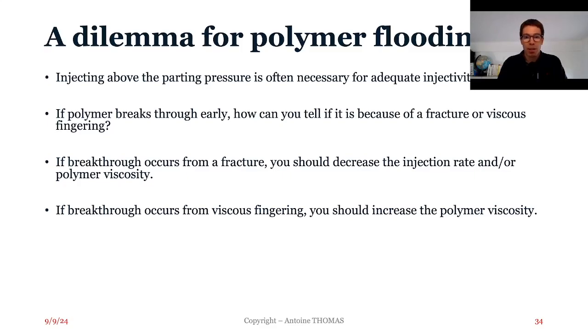The ideal case in a polymer flood is to never see the polymer in the producers. So it means taking sometimes aggressive steps to fix the fingers, to fix conformance issues, either by increasing the viscosity and making some slugs to slow down the propagation in these fingers, or to do some spot conformance treatments.